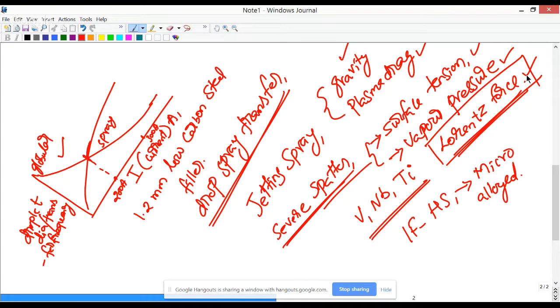Then question 8 in assignment 1, the austenite is retained in TRIP steel upon heat treatment by two ways, by carbon enrichment in austenite and by incomplete austenite to bainite transformation. So both are interrelated. So the answer here is the carbon enrichment of austenite, the incomplete austenite to bainite transformation, and then we can also get the answer C, retardation of cementite precipitation. So cementite precipitation also leads to carbon enrichment in the untransformed austenite. So you can say that incomplete austenite to bainite transformation, for which I already explained the incomplete reaction phenomenon.